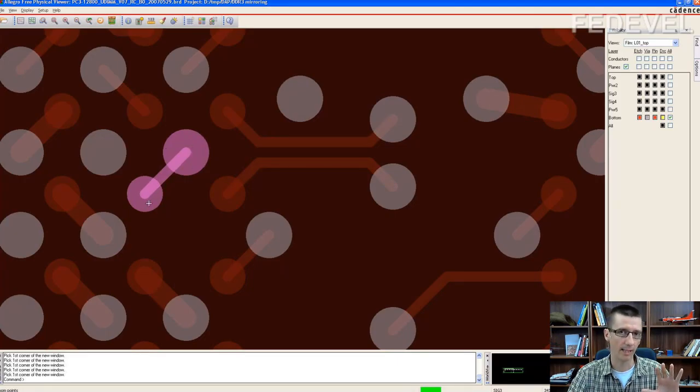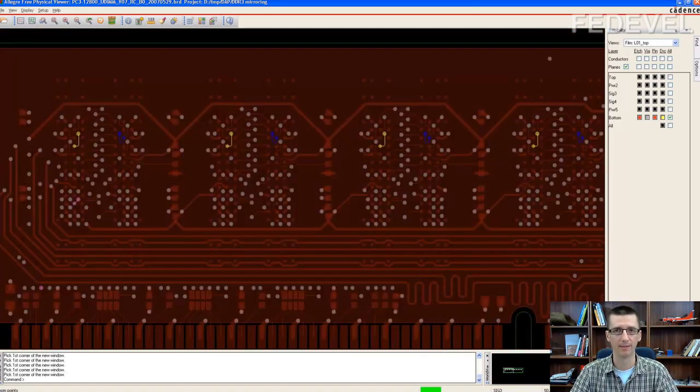Initially, you may have a different net, different data signal, but you go to the schematic, you do the pin swapping so that you will have here the net name, the signal, which is in this via, and then you can make the connection. So this is the proper way how you need to route data signals if they are shared between the top and the bottom memory chip.